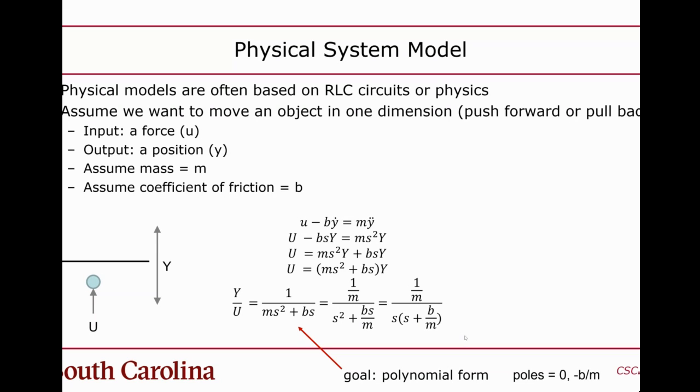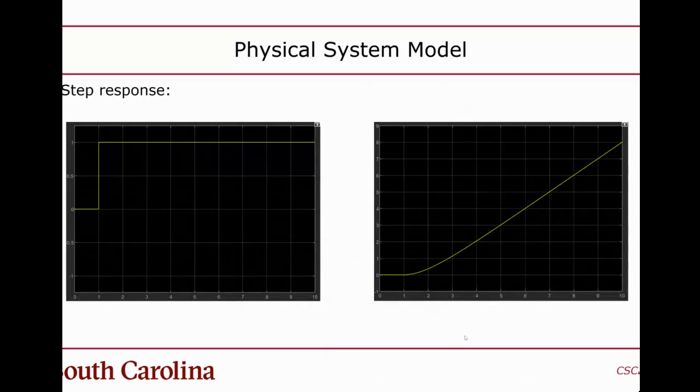What I've done here in this slide is I've used a glass box method where you know how the physics work based on first principles, which generally are going to be like Newton's laws, and then you build the transfer function that way. Another approach is a black box method where you have this device or this object and you hit it with some input stimulus and you measure its response. So that's another way to do it. There's two main ways to do it.